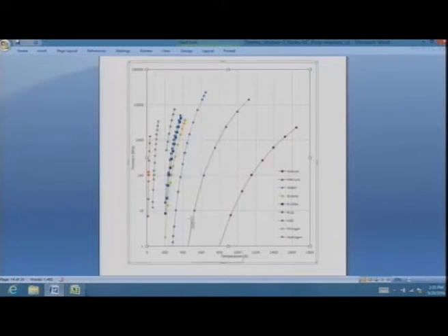But you can see that here now the temperatures have gone very high before we can even start thinking of mercury becoming a saturated liquid. So for instance, at 100 kilopascals, which is here, the saturation temperature of mercury is about 600 something Kelvin. It's fairly high temperature before mercury will begin to boil. And on the right is sodium. And here you can see that at 100 kPa, sodium will melt at about something like 1150 Kelvin. Fairly high temperature when it melts, and after that it can boil or change phase at constant pressure.